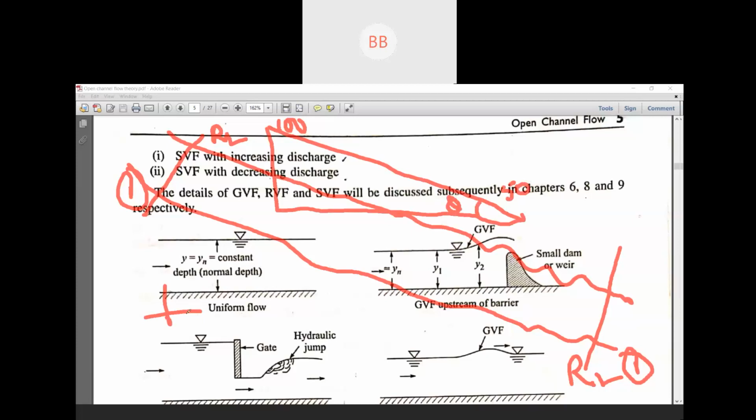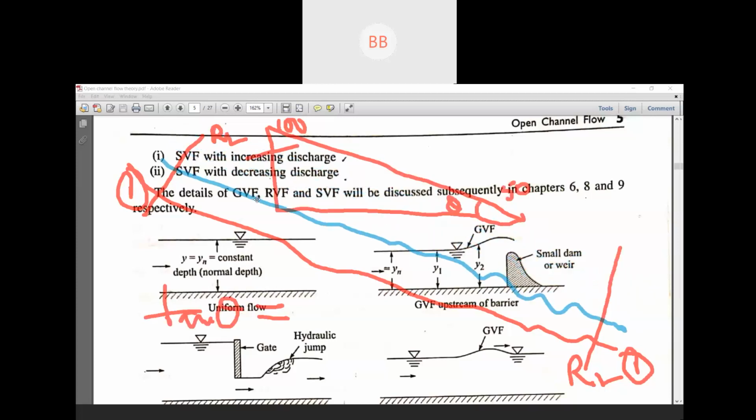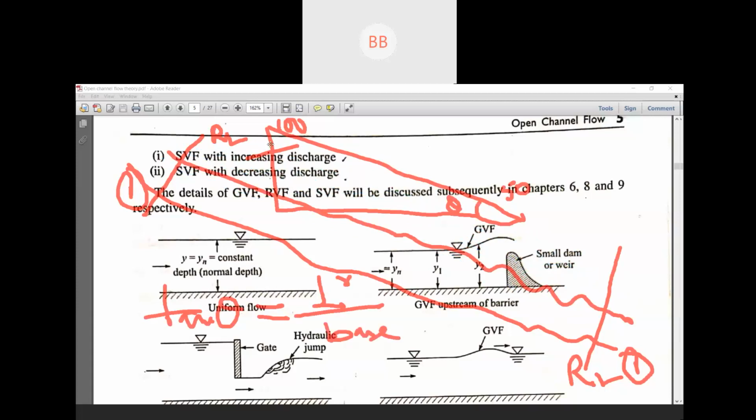That is tan theta. Tan theta is nothing but your RL. So what is tan theta? Tan theta is perpendicular by base. What is the perpendicular distance? This distance. Here RL is 100, here RL is 50, so this distance will be your 50 meter.